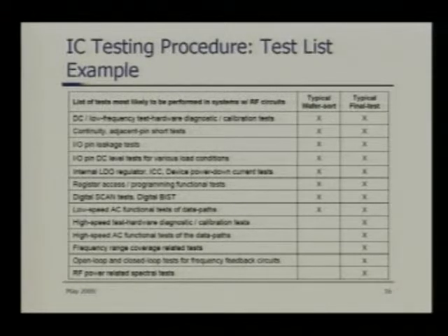What it means is that suppose you have put the device in the contactor and the contact is not good, so it may appear as an open circuit. Before applying, say, an RF signal, if the contact is not good, it's no point running your battery of RF tests. You first should better check the continuity, right?